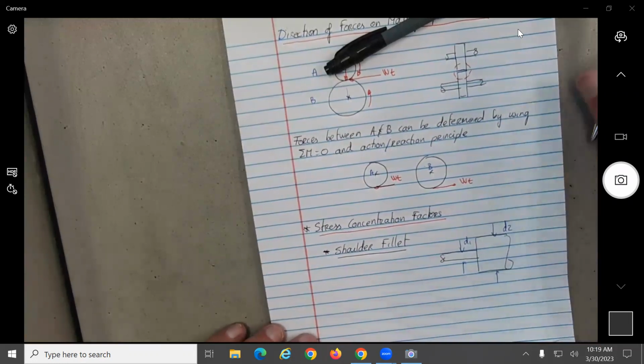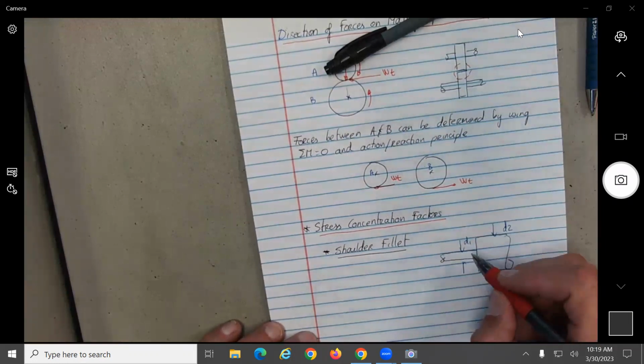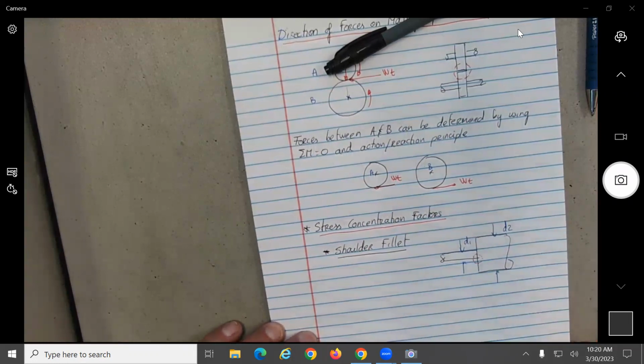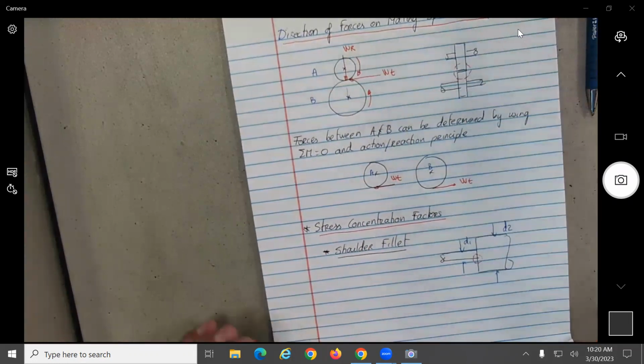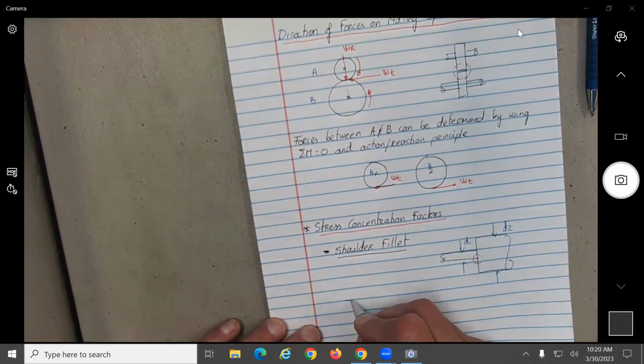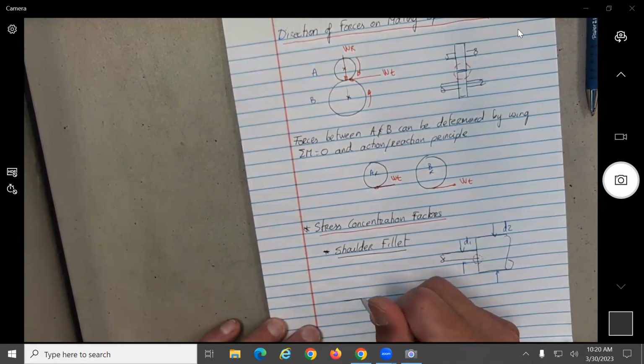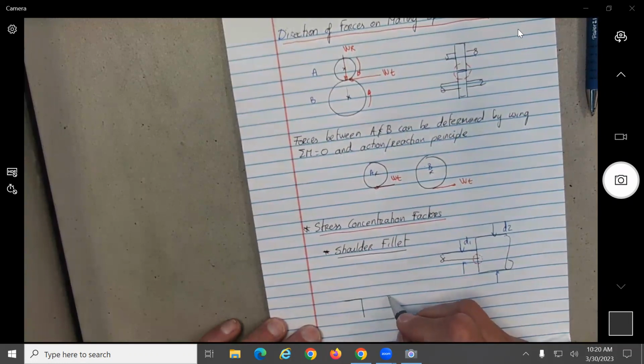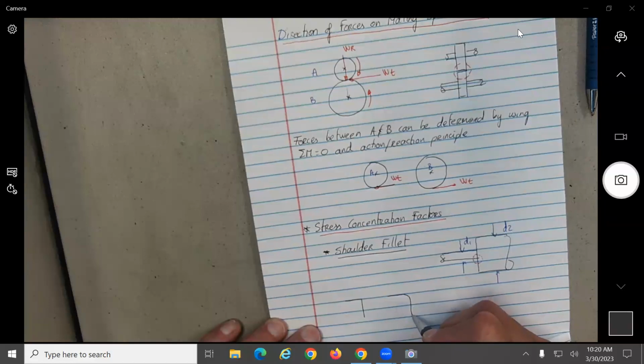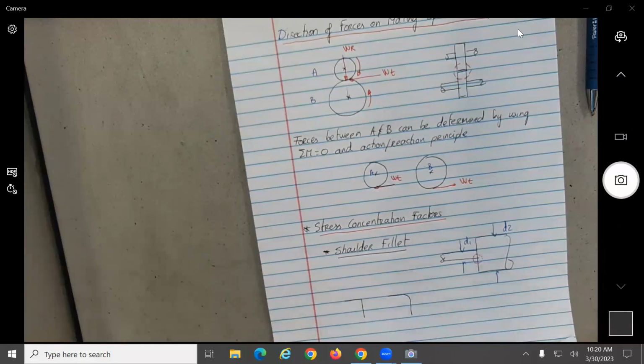And D2. And all this stuff is common sense, it's not rocket science, okay? I know you know this stuff, but for example, if you look at that, what is better to do? To have a sharp edge or to try to round it off? Round it off, no? And what is the reason? It's because you might have some stress concentration in those areas, no?